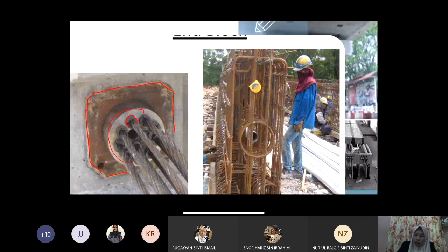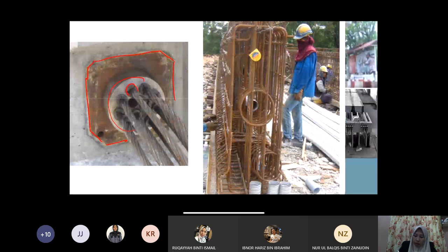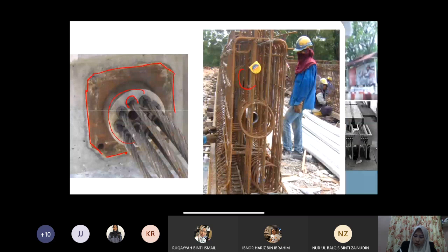And what you see here, this part is all the reinforcement provided at the end of the beam, for the end block. Just because you're going to pull the tendon, the anchor out, so it has to have proper reinforcement.